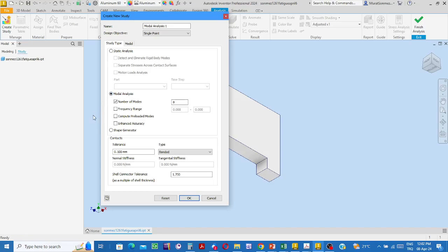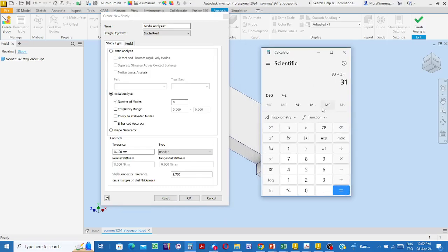Well, if we know the frequency of the load, for instance, the dynamic load will be exerted by a mechanism, and the dynamic load originates from a rotating body. What is that? For instance, it may be an internal combustion engine. Its frequency range is from 0 to, let's say, if it is the engine of an aircraft, the number of RPM may be in the order of 30,000. 30,000 divided by 60, 500 hertz.